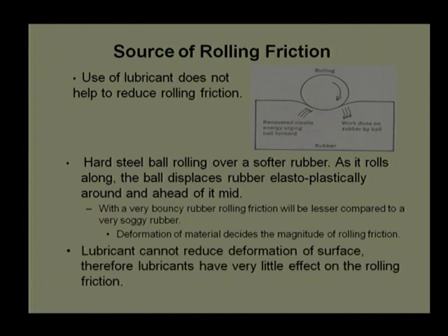And again the same line applies: lubricant cannot reduce deformation of the surface. Therefore, lubricant has very little effect on the rolling friction. It will not be able to reduce the coefficient of friction substantially.